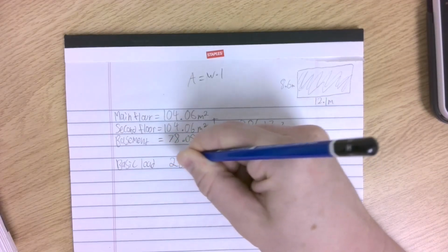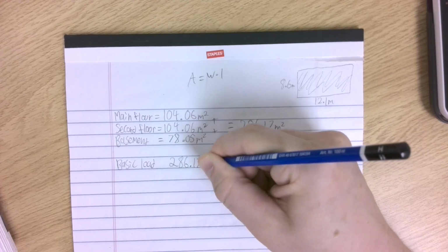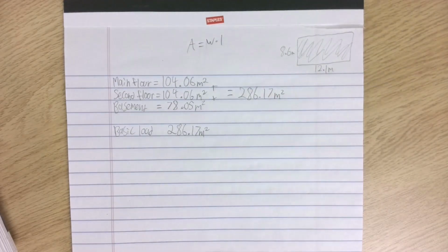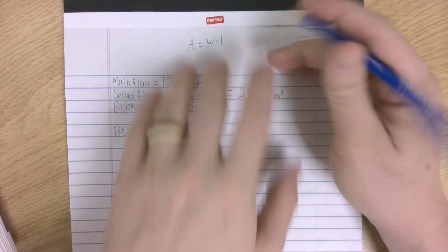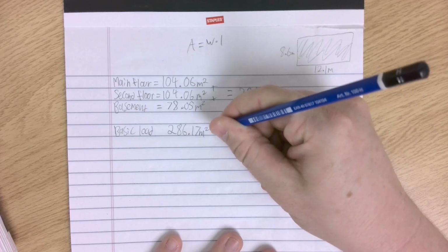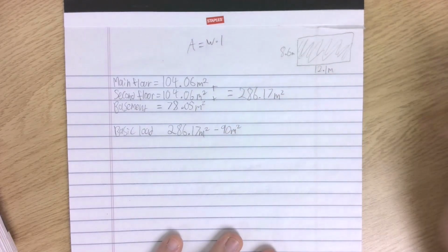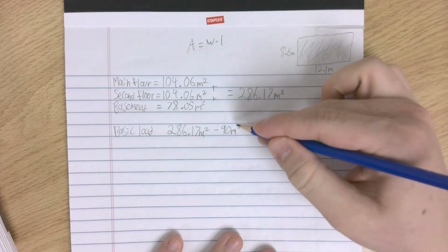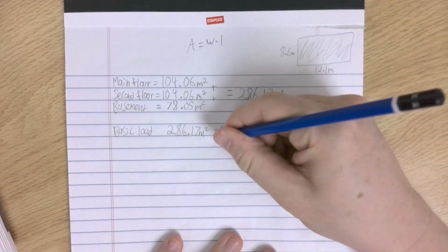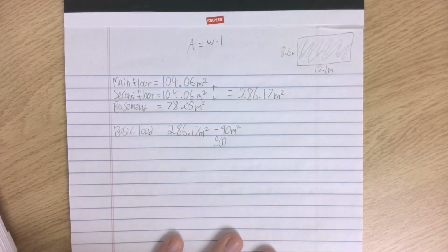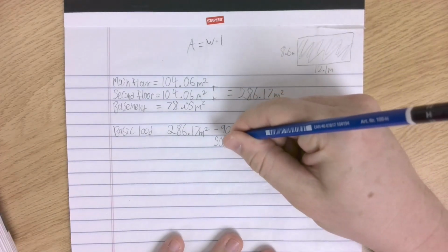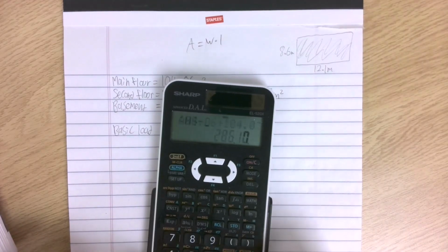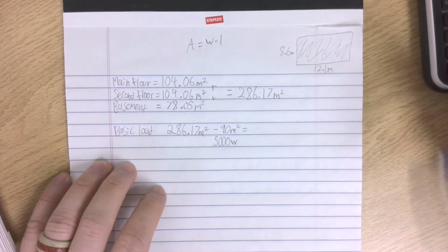So this is how I make sure that I personally count the right amount of watts for the basic load. So the first 90 meters squared. What I do, and you can do it differently if you find a better way, is I minus 90 meters squared, and that's my first 90 meters squared that I'm accounting for. And each time I subtract 90 meters squared, I put the wattage associated with that based on item I and item II, or 2 I should say. And so the first one is 5,000 watts. And so 286 minus 90 equals 196.17. Perfect.